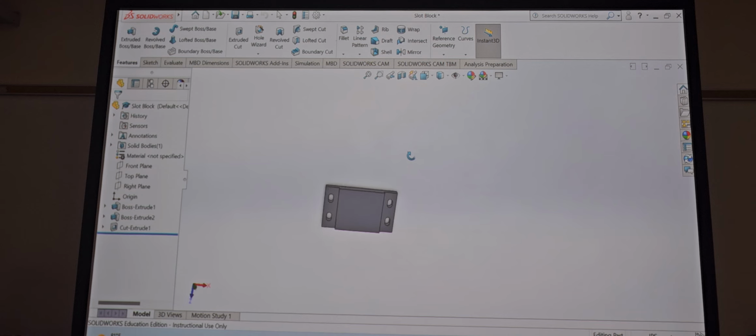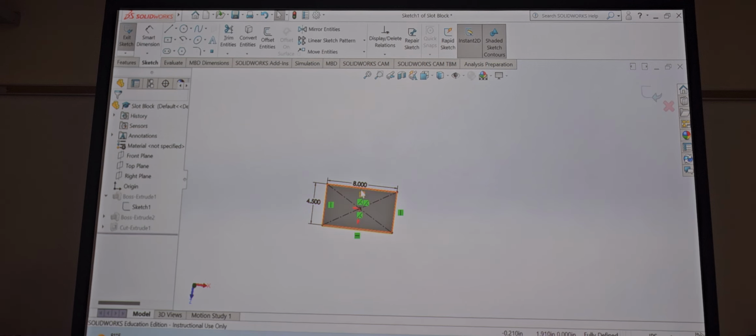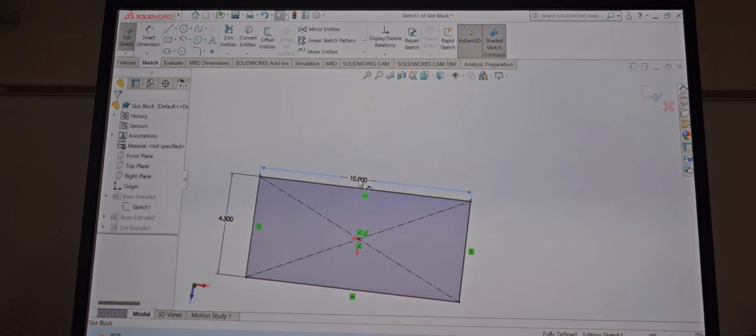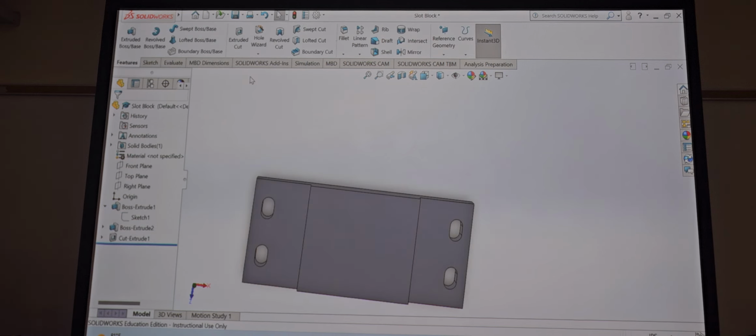And remember guys, if you messed up on your drawing and you need to edit this one, you just go to your features that you had to edit. If that was 10 inches long, I'll push this arrow, come back to sketch, edit my sketch. Hey, the engineers really wanted this one 10 inches, not 8 inches, right? So we go to 10 inches, hit enter, it moved it. We gotta exit the sketch though, for it to follow on the other side, right? So we exit sketch.